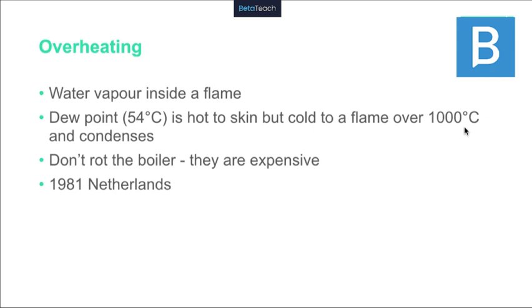And unfortunately, the BS 7593, which is the standard that the inhibitor companies wrote, doesn't mention temperature, which is quite strange considering we're all talking about temperature now. You bring your temperature down, you reduce your rate of corrosion. It's simple laws of physics.